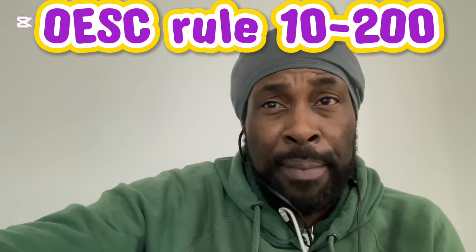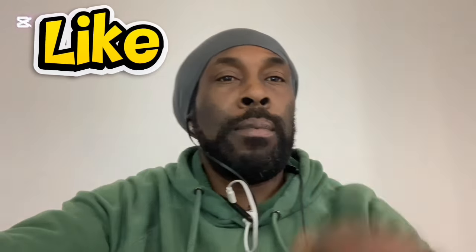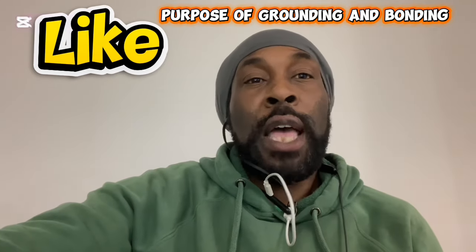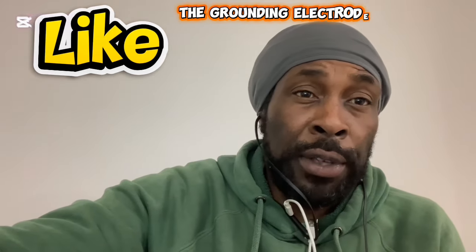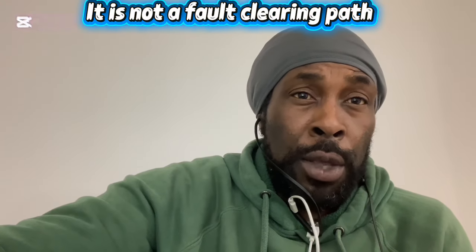OESC reference Rule 10-200/10-204, purpose of grounding and bonding. This is a big misconception. The Grounding Electrode Conductor, the GEC, does not trip breakers. It is not a fault clearing path. The breaker trips through the equipment bonding conductor, not the ground rod.